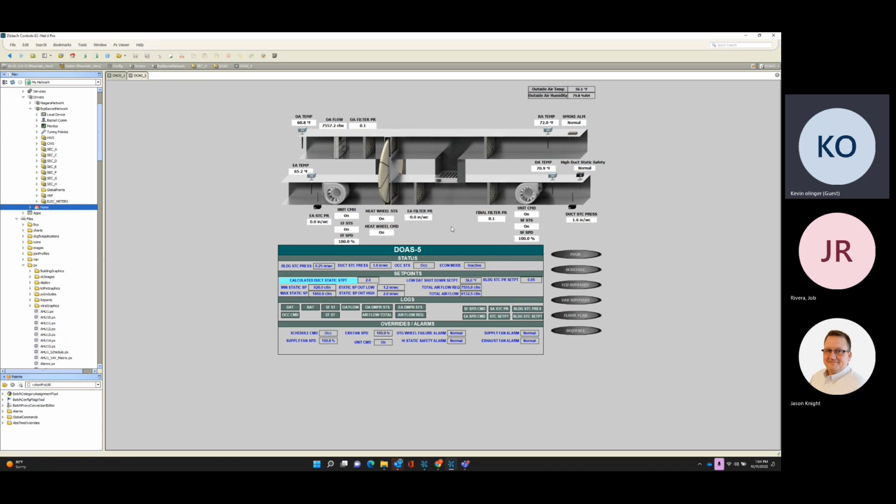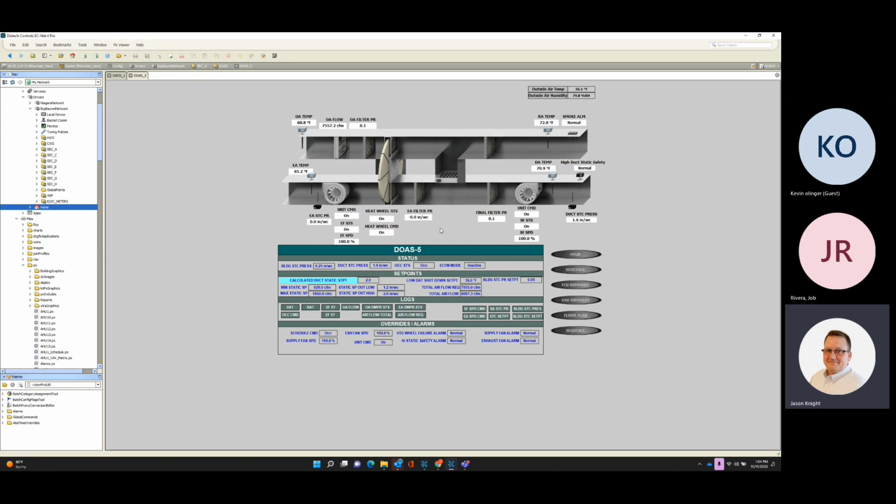But keep in mind, if a DOAS is not running, we can't occupy. So there may be times where we might have to override that and sacrifice that and keep an eye on the coils just to keep the building occupied. So if it remains, obviously it needs to be in the sequence of operations, and it'll need to be an alarm point that flags us, like you're saying, turns red to tell us that we're in that condition. Right. These wheels are pretty impressive. The energy recovery on them is huge.